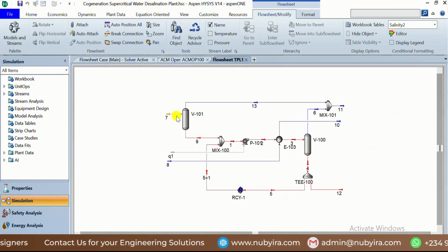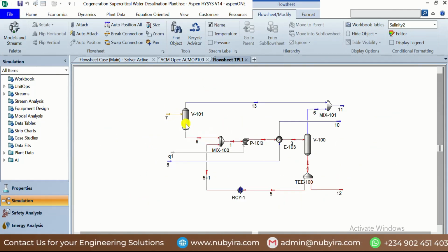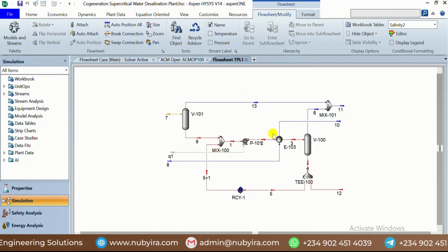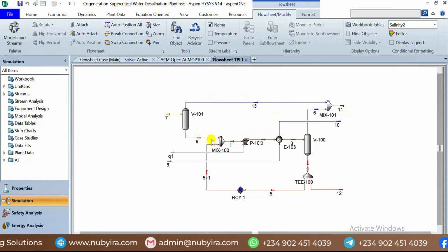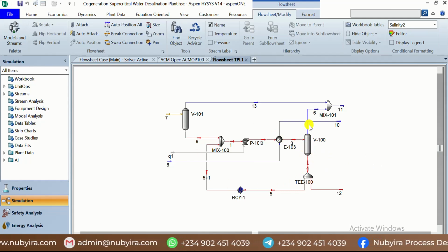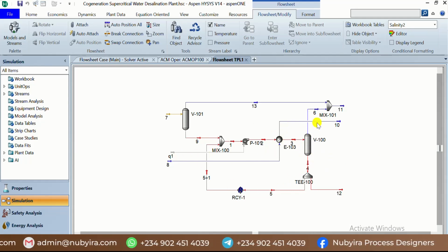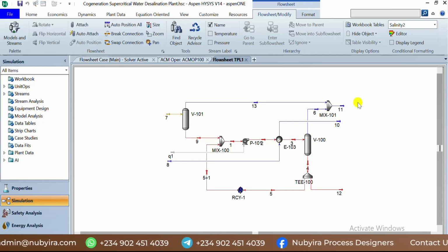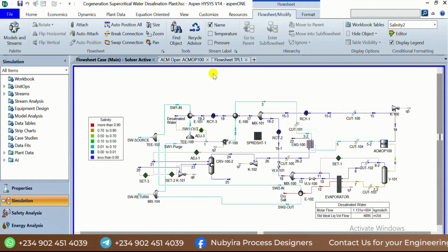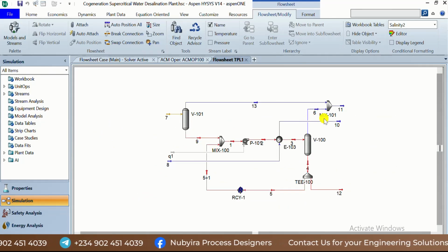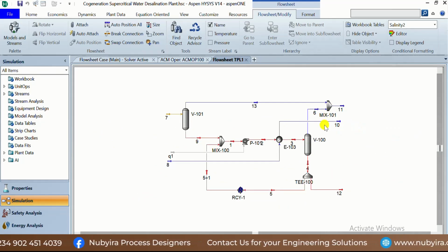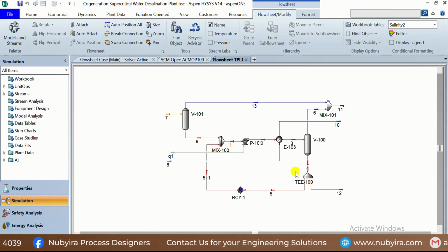In the forced circulation evaporator, you have the brine, we flash again to get more steam, and the brine is circulated through the evaporator tube and heated using the steam produced from the first stage plant. This steam is used to heat up the brine in the first evaporation, so you are not using any other external energy, which makes the process efficient.